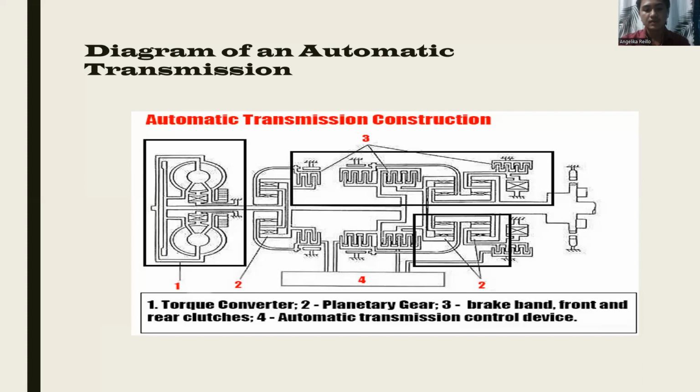Number 4. The automatic transmission control device is a unit responsible for control and consists of an automatic transmission pan, a gear pump, and a valve box. The torque converter transfers engine torque to an automatic transmission element, smoothing engine vibration and driving an oil pump. The oil pump generates the operation pressure of the transmission fluid in the torque converter and control and monitoring system, installed in the housing between the engine and the gearbox, and operates the clutch function.